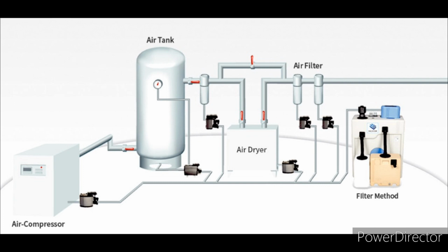Okay, this is the explanation about auto drain valve, and I explained the working principle and function and applications, and what is the difference between timer controller solenoid with timer controller auto drain valve and zero loss auto drain valve. So as per my suggestion, go for zero loss auto drain valve because breathing air is free, atmospheric air is free, but when we compress that we put some energy, so we don't want to waste that energy.